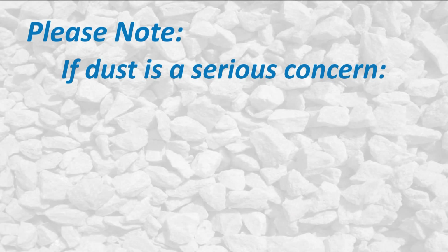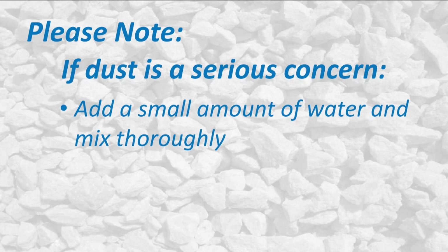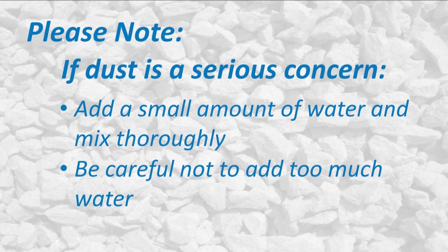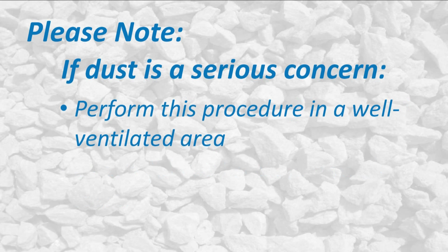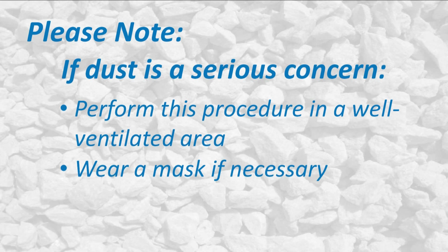If this is a serious concern, then add a small amount of water to the original sample and mix thoroughly before splitting the sample. The extra moisture will prevent many of the fines from becoming suspended in the air and drifting off. Remember to not add so much water that the moisture content ends up being at or greater than the SSD condition, in which case the mechanical splitting method would no longer be valid. In any case, be sure to perform the splitting procedure in a well-ventilated area while wearing a suitable dust mask.